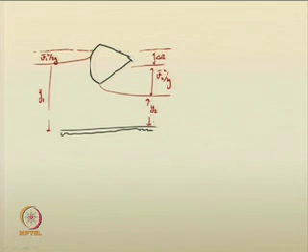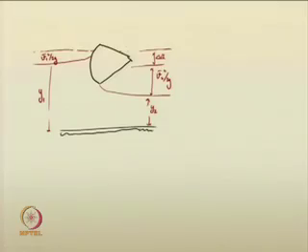Like this you can think about it. Such a structure is a tainter gate. Compared to the sluice gate, it has more span, and it can be used to control large volumes of water also.